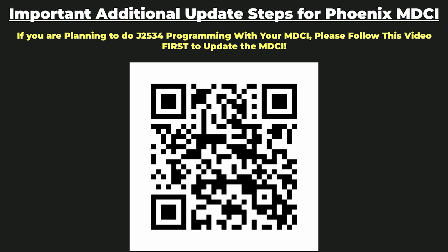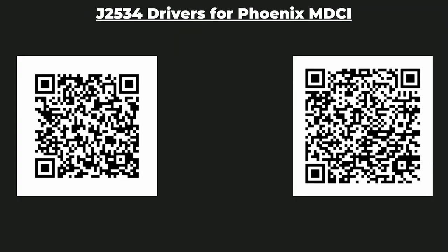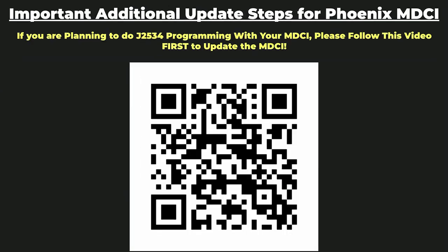So you can hit these QR codes on the previous slide here for the drivers, and you can hit this code here for a video on how to perform the update process on the MDCI related to plugging it into Ethernet and plugging it into a power supply. So again, both of these steps need to be done before we try to do J2534 programming with our Phoenix MDCI. So again, just some very important notes we want to keep in mind before we try to do programming with our Phoenix MDCI.